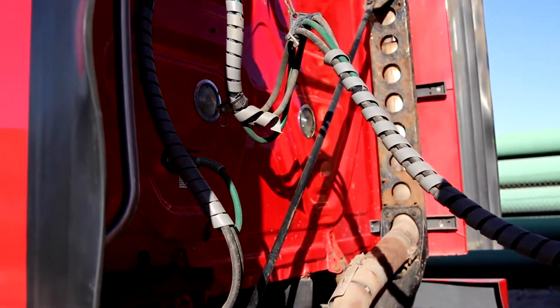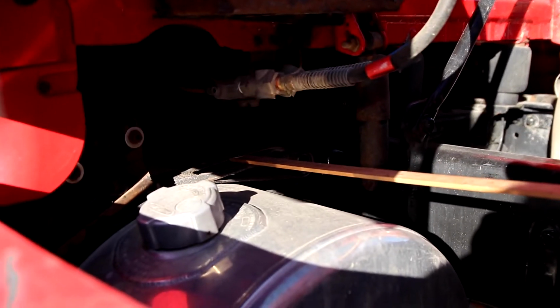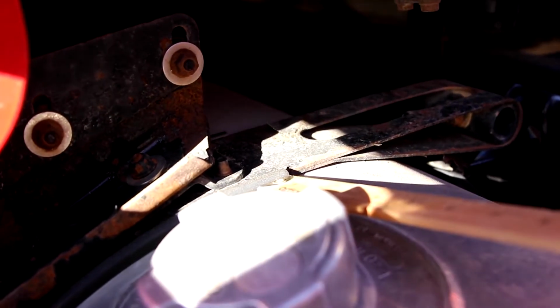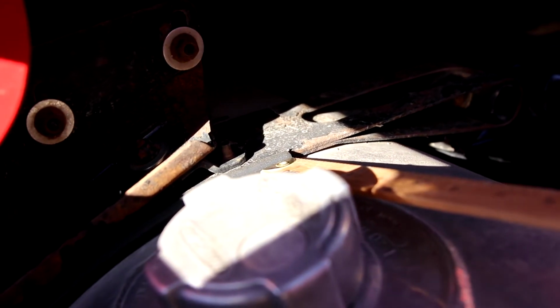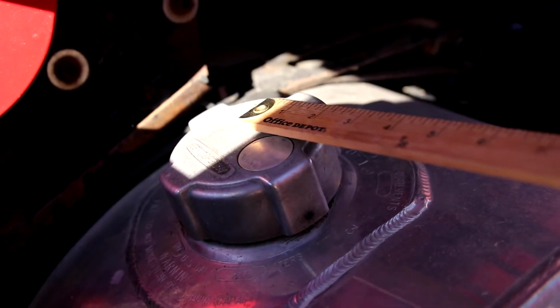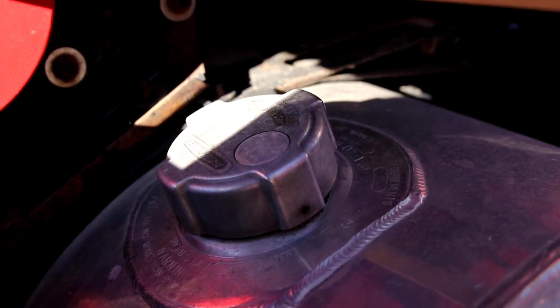And you have your fuel tanks mounted left and right. They're held in place with straps, and they should have a static strap. That's that rubber piece right here that I'm pointing at. Mounted securely to the vehicle, not missing, damaged, or broken. It has fuel in it, so no leaks. And it's topped off with a cap. The cap should have a rubber seal and a chain in it. And again, there are no leaks.